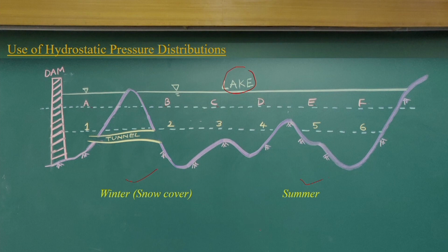As we know, along a horizontal surface the pressure will be the same when the fluid is at rest. Otherwise, the fluid could not be at rest if there were a pressure difference; the fluid would start moving. So, for any horizontal surface, when the fluid is at rest, the pressure on that surface becomes equal. Mathematically, that means PA, PB, PC, PD will all be equal, as they are on the connected surface.